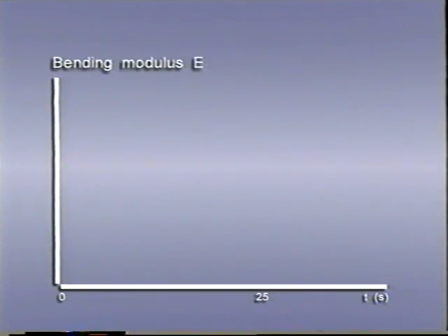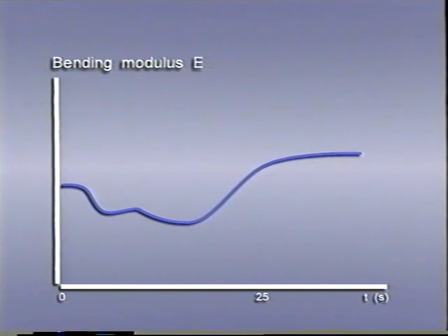As the molecular structures change, so do their mechanical attributes. To begin with, we can examine a considerable softening of the resin in the flow phase. Afterwards, as the molecular cross-linking continues, we observe a rapid increase in the material's stiffness and hardness.